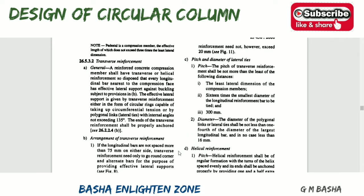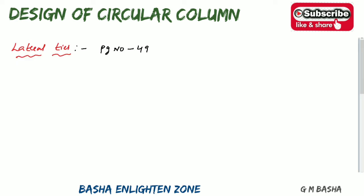Already in the last class itself I told you it is 6 mm, not 16 mm. So first, based on that, what they mention in the diameter column is 1/4 of the diameter. The diameter of the lateral tie should not be less than that. That is the first step. So what diameter have we chosen here? We have chosen 6 bars of 20 dia.